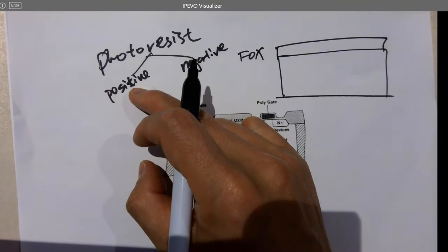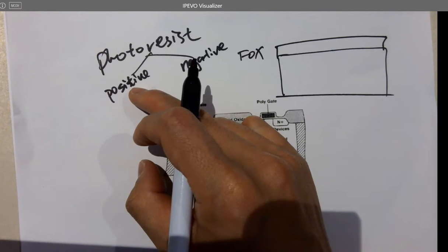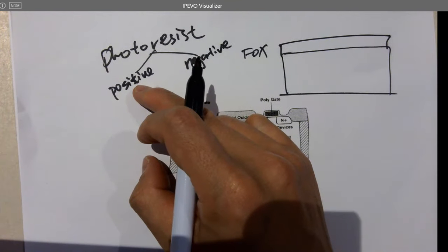Spin coat it. So you get a very uniform thin layer of photoresist on the top. Still honey material texture, and then put in the oven to cure it, so it becomes like a plastic texture.